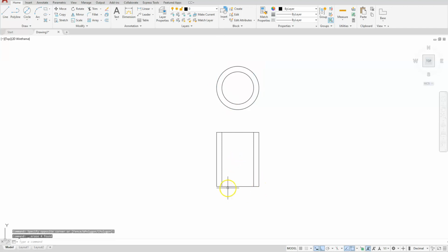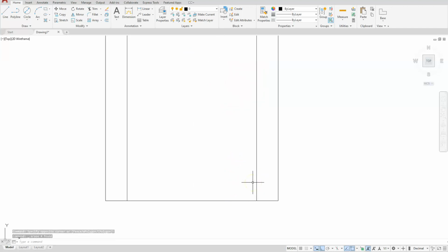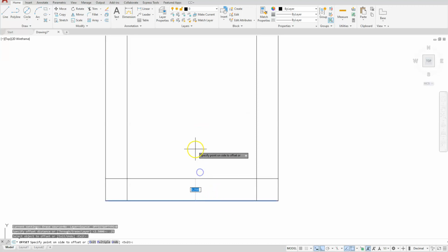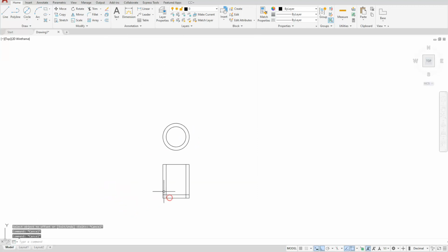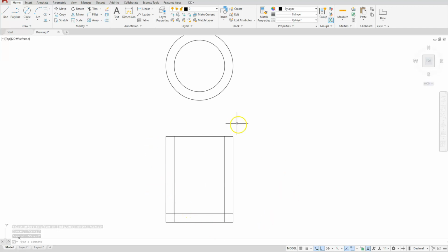Now it doesn't tell me where the bottom of this cup is, but if you assume that it's 0.25, that's safe enough to assume in this case. So I'm just going to offset a distance of 0.25, this line going up. Okay. So now that I have the walls that I need to create my cup, next, let's start going ahead and building our handle.